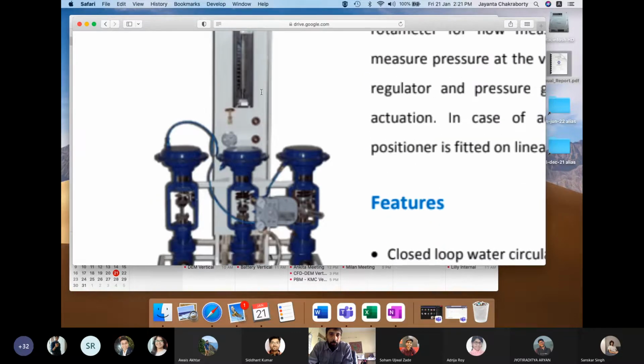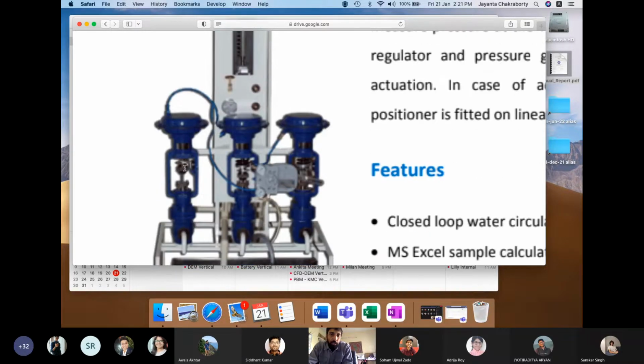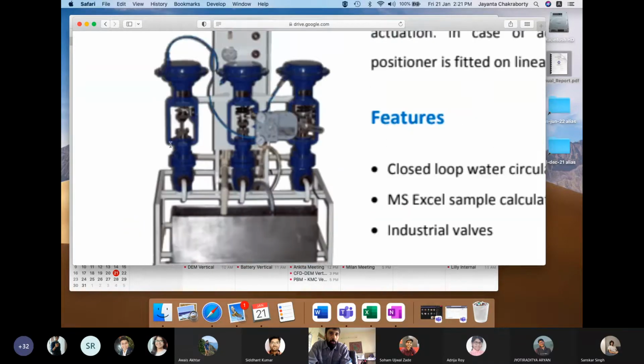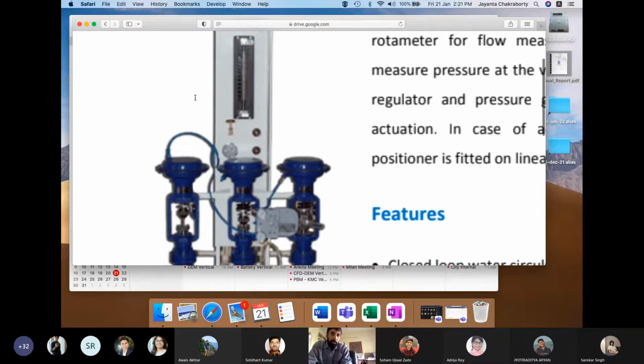So that is the pressure, and the signal that comes here, there are two air regulators, from which you just move the knob, you'll be able to control the top pressure. So that's how you move the stem up and down and change the percentage lift. And this pressure gauge reads the supply pressure. There is a compressor here, not shown. This compressor gives the supply. So these blue lines are all pneumatic lines. So blue plastic tubing, those are pneumatic lines. And this reads the supply pressure.